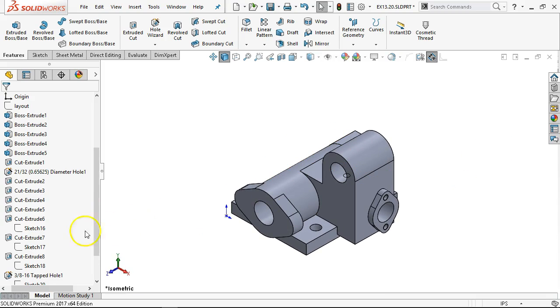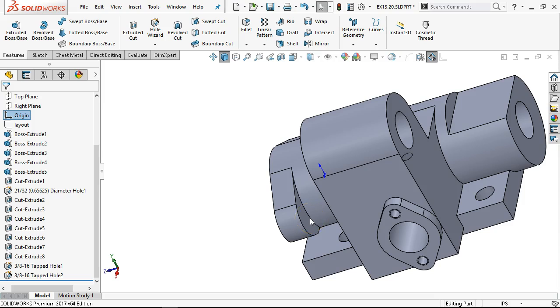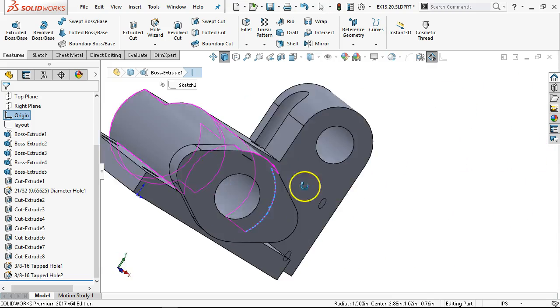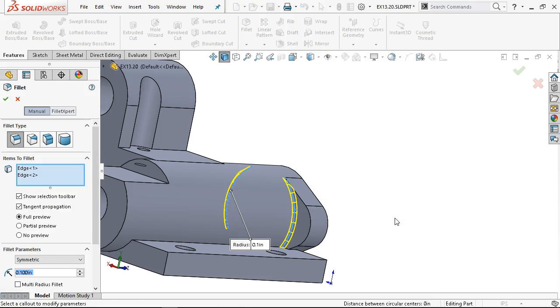Alright, so the issue with the last 3/8-16s on the face is when they penetrate through the backside. If the fillet's there, it's going to not show geometry, I guess that's accurate. So I don't necessarily have to put in all of the fillets, but I do need those fillets in place before I make that intersecting cut.